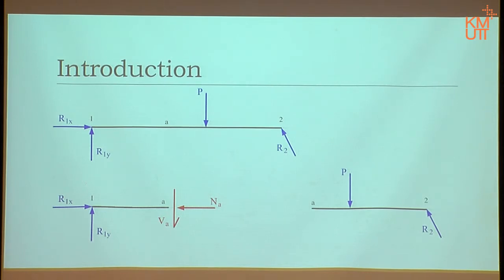Is it in equilibrium yet? No. Why not? Because apparently that R1y and that VA create what we call a couple of forces. If there is a couple, there must be a moment. This body, without movement resisting it, is going to rotate in a circle. Therefore, there must be a certain reaction happening inside the material, again in the moment form.